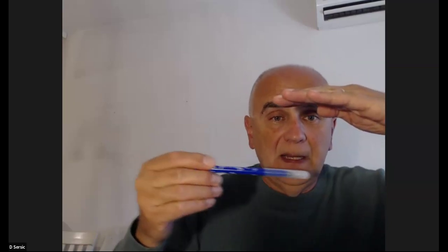almost perfect reconstruction. But the best idea was, okay, let's use lousy filters, but let us design them in such a way that the aliasing parts from one branch cancel the aliasing parts from the other branch. Even if we have 10 branches in some systems, maybe we can design the filter bank in such a way that the aliasing parts cancel each other. And that was the most brilliant idea that will bring us to decimated filter banks that are useful, and they have the exact perfect reconstruction property.